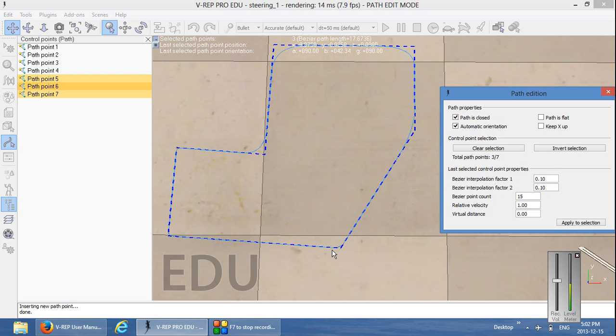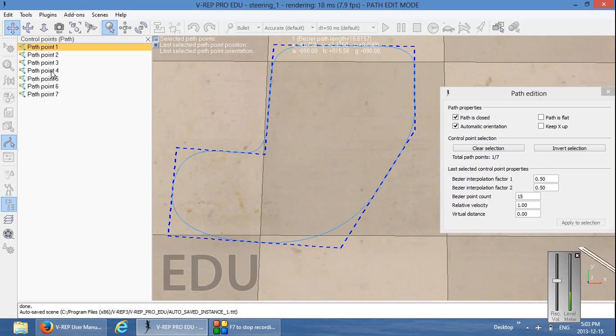Not many robots will be able to traverse them perfectly, and it's really up to you to check with the competition guidelines what is the minimum radius that will be given to you. So let's change it to 0.99, and you will see that these corners are now very large and easier to traverse for many types of robots. Since you're using an Ackermann steering car, they are a little bit less agile when it comes to corners. So we'll actually set all of the corners quite large.